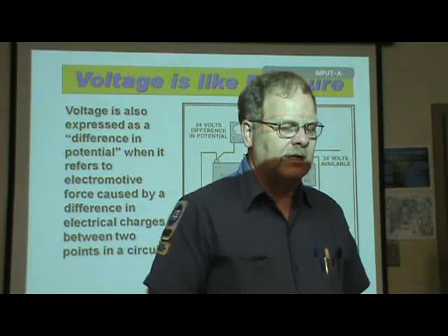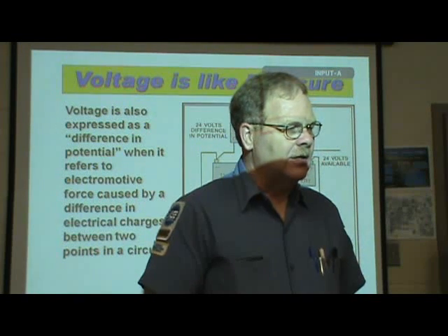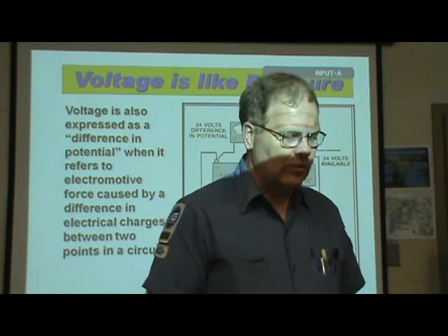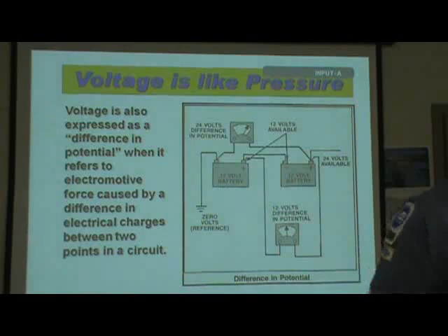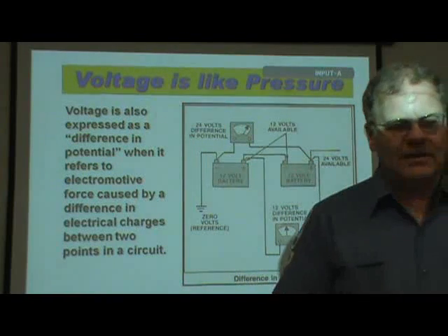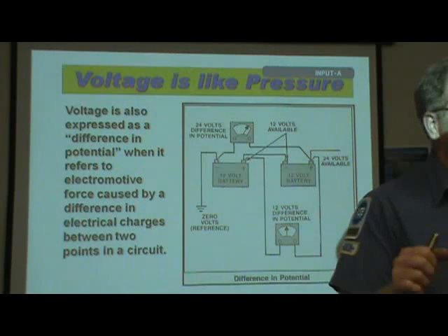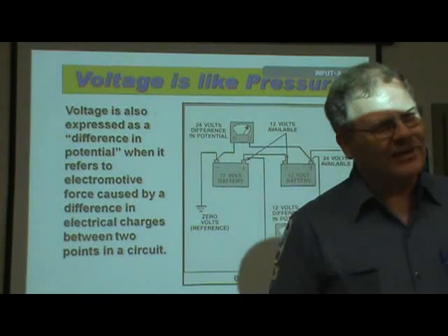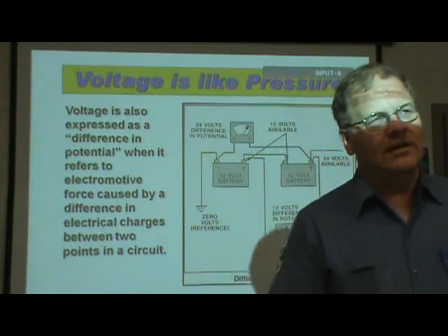If we had an engine that was spinning really slow, sometimes when somebody has tried to start an engine and fuel keeps squirting in there, it washes the cylinder walls down on one of these older vehicles that's got the high tension piston rings. Have you ever heard one that somebody's trying to start, it's been sitting a long time, and it just turns real slow, and you're sitting there saying, what is up with this? Whenever you're driving a car every day, it fires right up. Well, this one turns real slow.